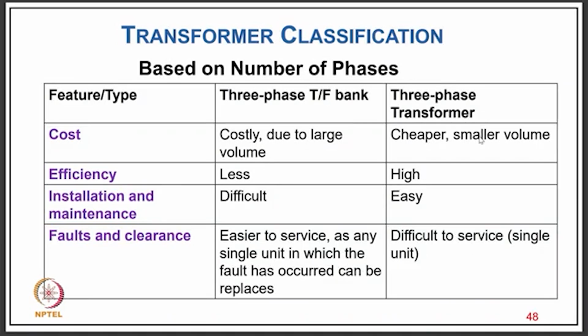Well, you can have a 3-phase transformer bank consisting of 3 single-phase transformers, or a 3-phase transformer; a comparison. First is the cost. Cost is large due to the large volume of 3 single phase transformers, and the 3-phase unit is certainly cheaper and smaller in volume.